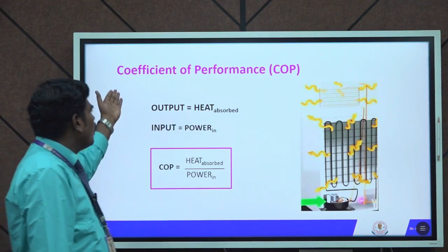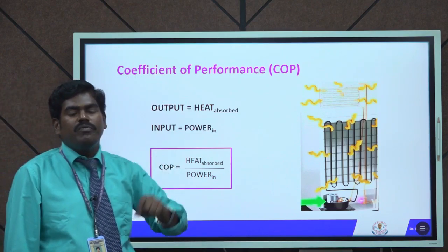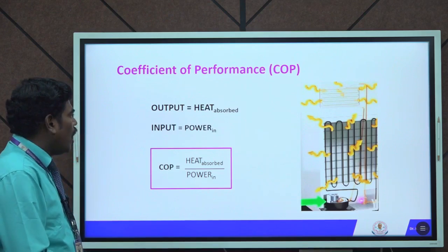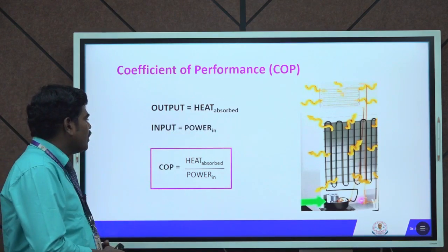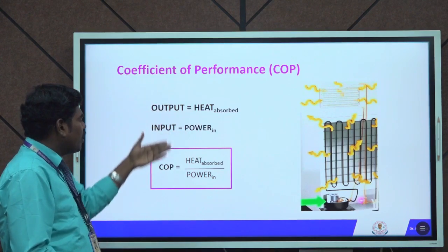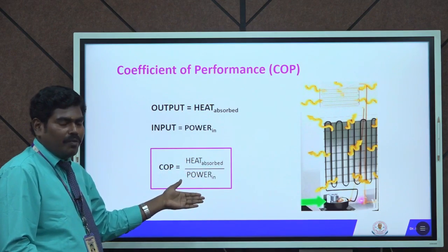Let's see one important term, the coefficient of performance. This term is used to evaluate the performance of a refrigerator. The output is evaluated by the heat absorption process, and the input is evaluated by the power input. The coefficient of performance equals heat absorbed divided by power input.